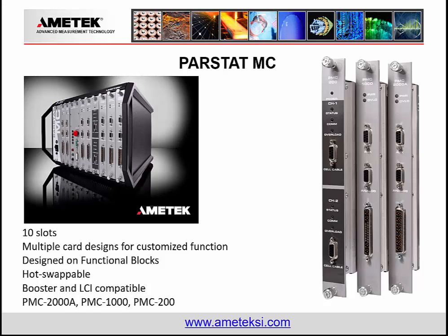The PARSTAT PMC 1000 provides us 2 amps per channel, as well as booster capability, LCI capability to expand its current ranges. And the PMC 2000A provides us both high voltage, 30 volts on board, and 6-wire capability. So that's 1 additional electrometer when we're making those measurements, so it's capable of doing anode-cathode tests or a single cell within a given stack.